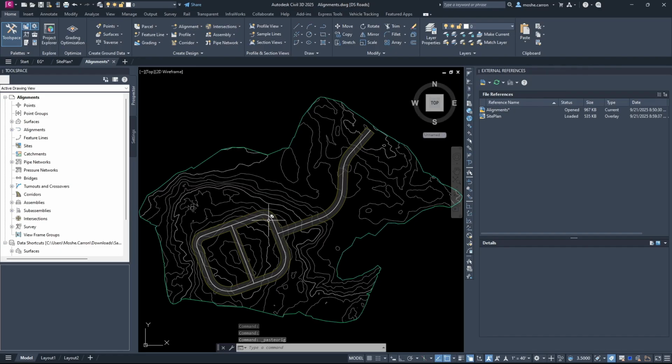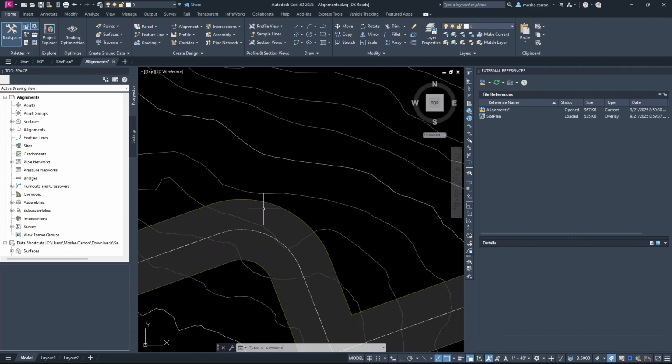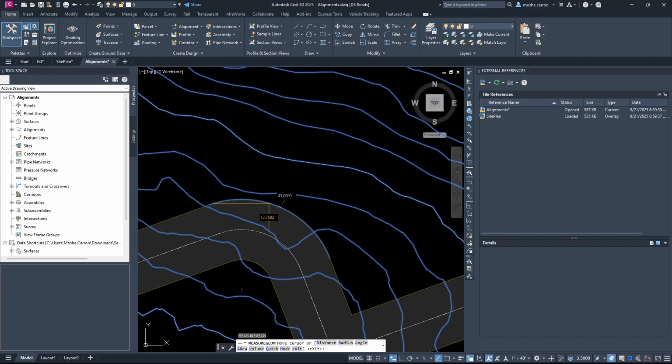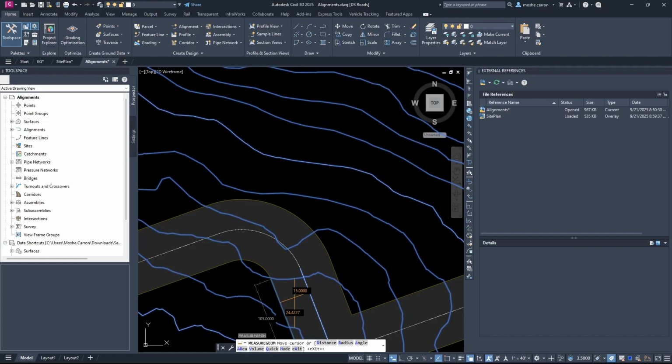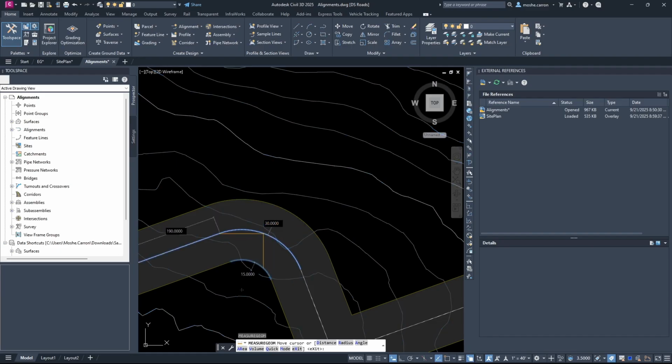One thing to note with center lines is when you have a radius, such as the outer one: if I use the measure geometry tool, I have a 45 outer, a center line of 30, and an inner one of 15, thereby telling me that this roadway has 15 feet lanes on each side, so 30 feet total. As with curb radius, you want to add the width of the road to your radius. If the radius on the center line was 15, it would be an abrupt 90-degree turn. Just an FYI.